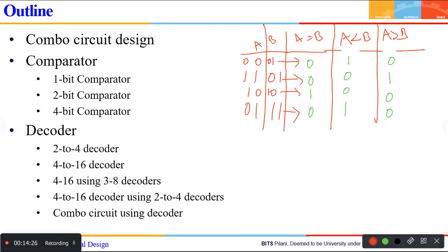You have, in between here, something called a 3 to 8 decoder, a 4 to 16 decoder. Now similarly, assume that you want to design a 4 to 16 decoder but 4 to 16 decoders are not available. Do you stop your work? No. You can construct a 4 to 16 decoder using 3 to 8 decoders.